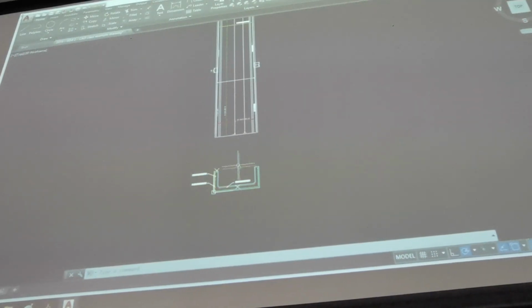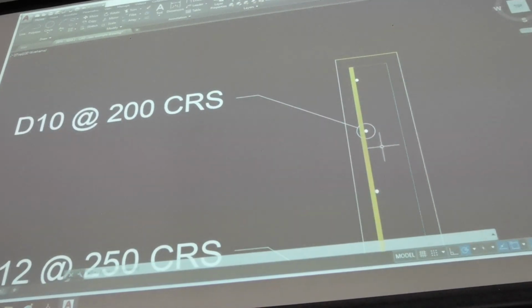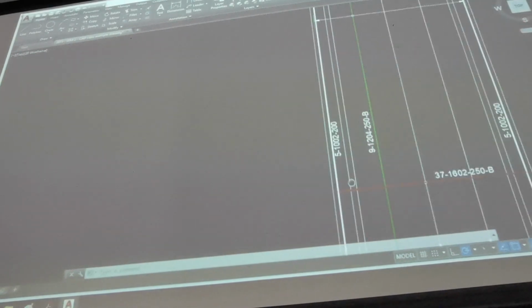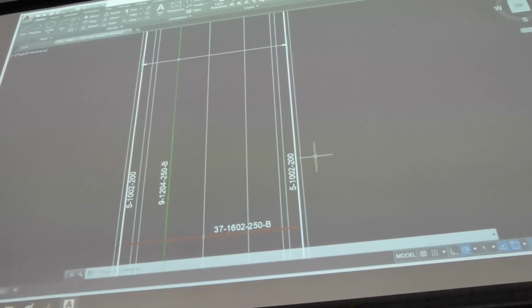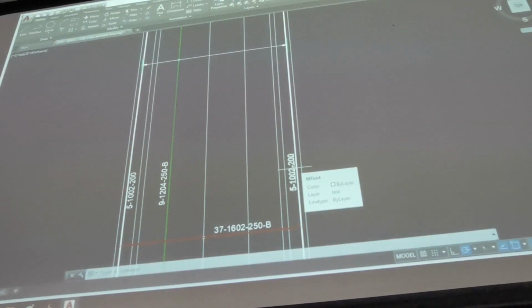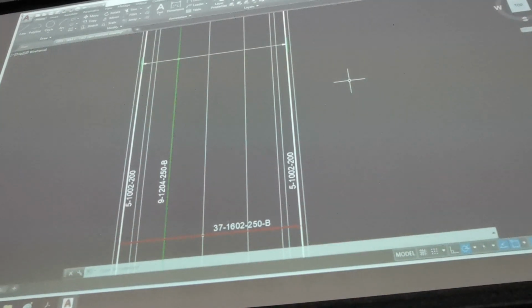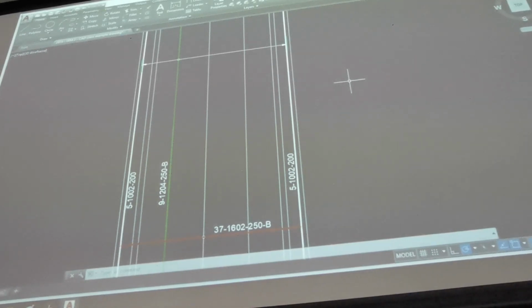Now, I want you to note that on your schedule, it showed 20 of these bars, but on the drawing, we showed 5 there, 5 there, 5 there, and 5 there because they lap. Okay? Now I'm not going to say any more, but you're going to have to work out the differences between your bar schedule and the numbers and how you show them on your drawing. In some cases it's the same. In some cases you might have to split that into 2. And in other cases it's completely wrong. It's completely different.